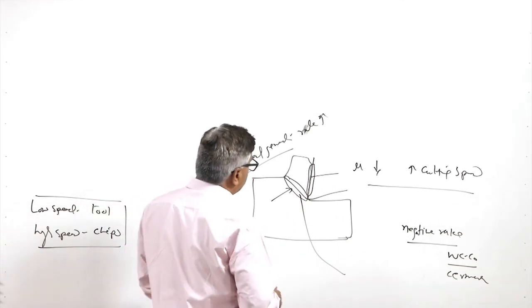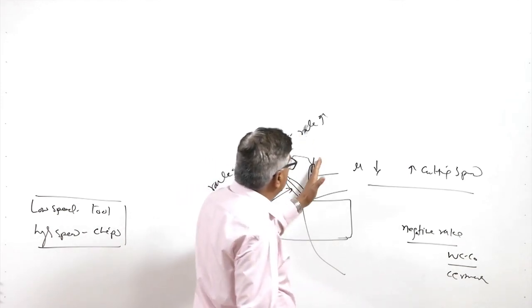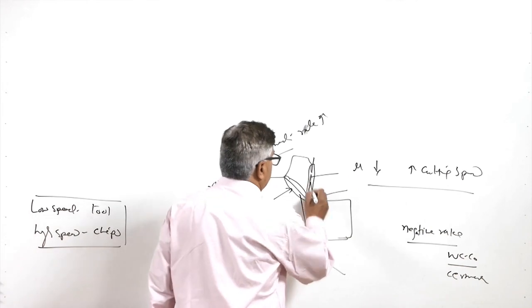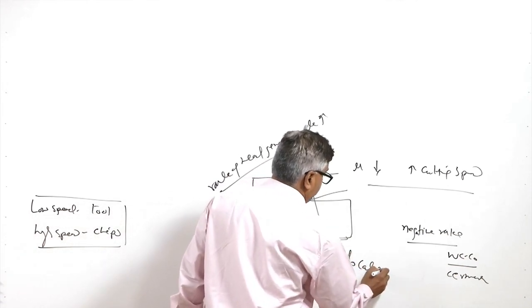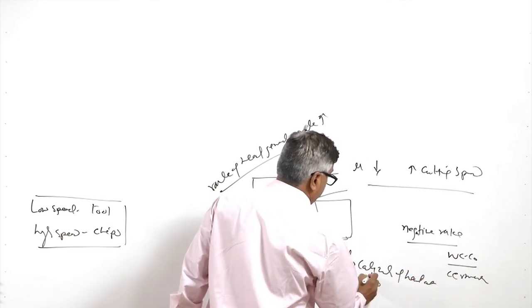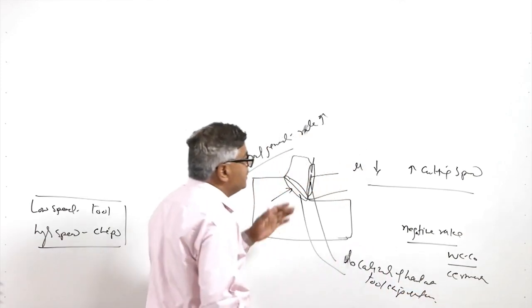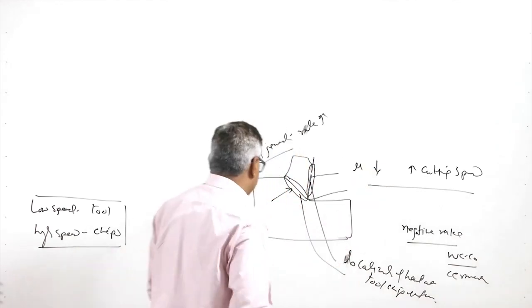The rate at which heat is being generated per unit time increases. So, the tool does not get much time for transferring the heat away, and this leads to the localization of the heat at the tool chip interface. So, this localization leads to the rise in temperature with the increase of the cutting speed.